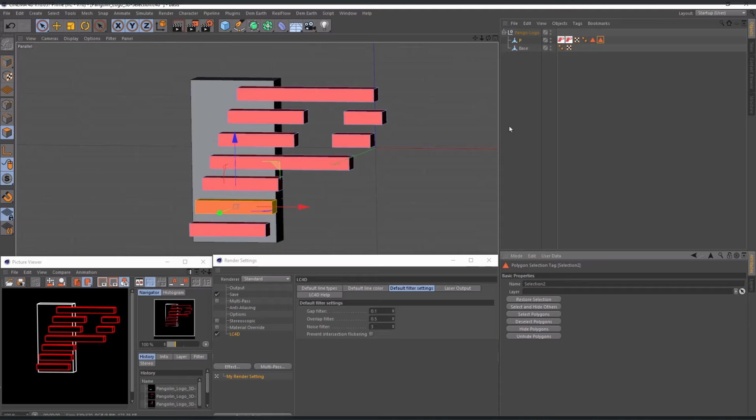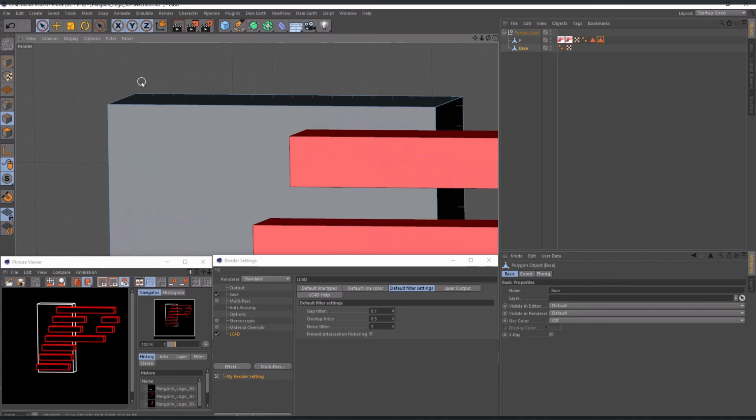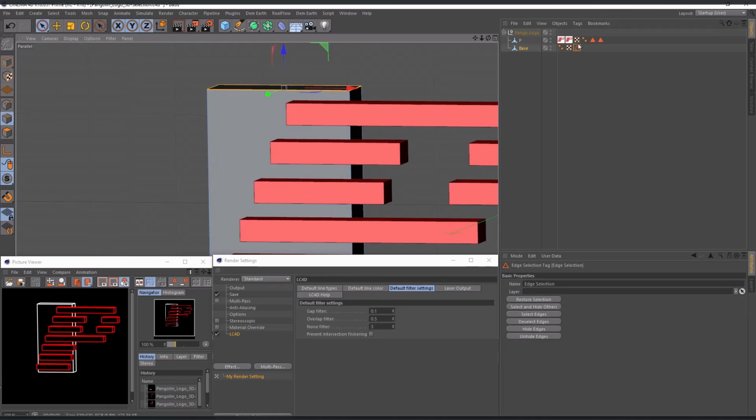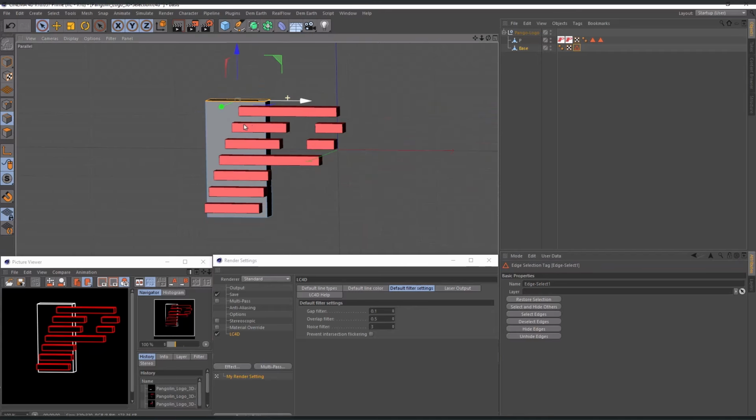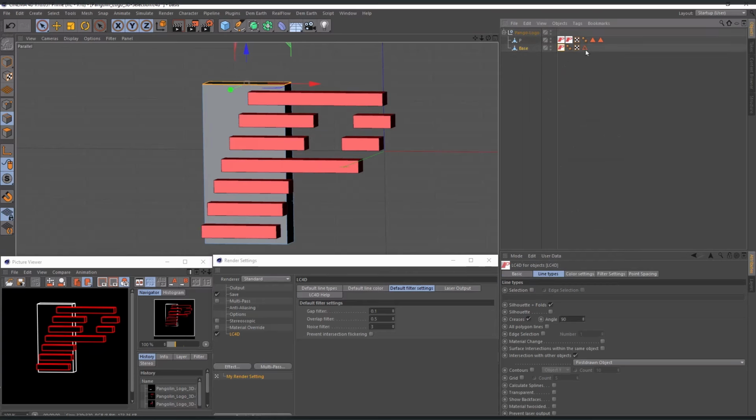And now finally, I would like to include another selection inside this gray base block. And therefore I will now choose the edge selection tool. And here also easily marking four outer edges of this last block. And we can also see this selection here selected as edge selection. So let's simply call it Edge Select 1. So we now have three separated selections, and for the second base object I need to include another LC4D tag so that we are able to customize its render settings individually.